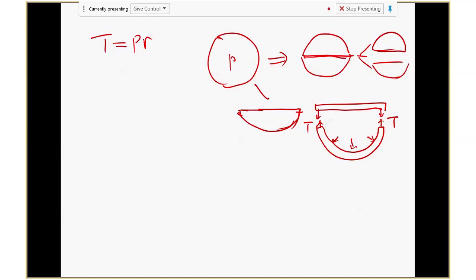Now, can I quickly find out T? Yes, the quick way is, instead of calculating this one, where you have to do this integral, because every element changes direction and you have to project sine and then do this, right? Now I can easily do it on this one. Imagine you have this vessel, so inside is P. So on here, it will be also pressure P. Now let me redraw this plate.